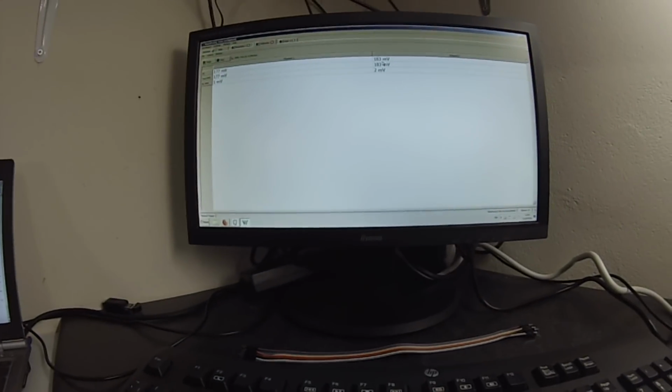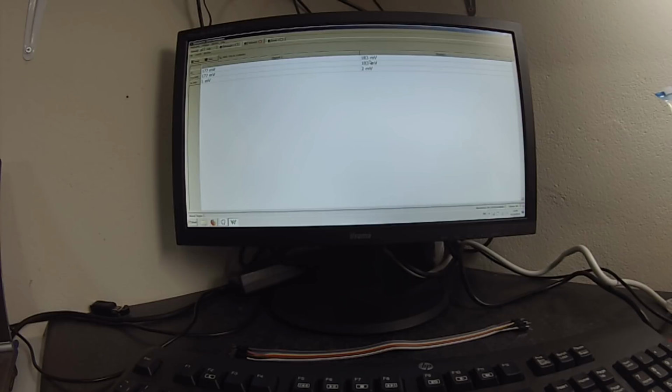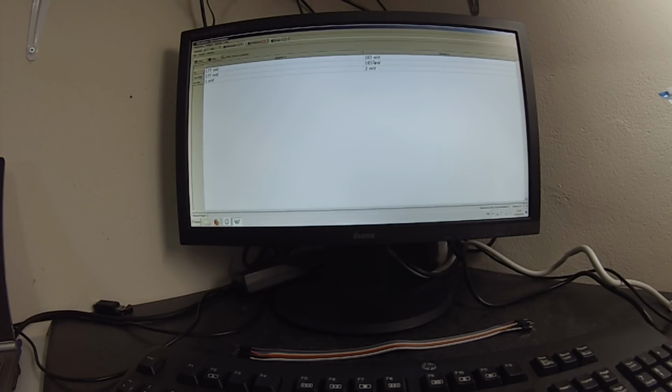So this means that our signal conditioning circuit and our window comparator is now working not just up to 900 amps but up to slightly over 1200 amps.